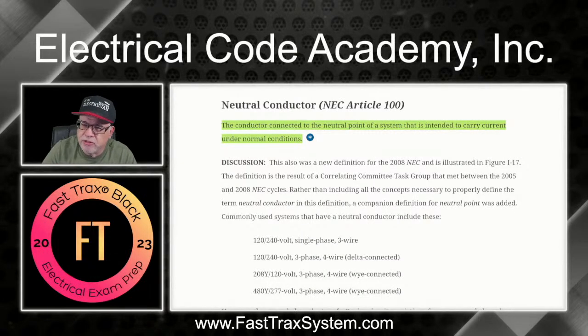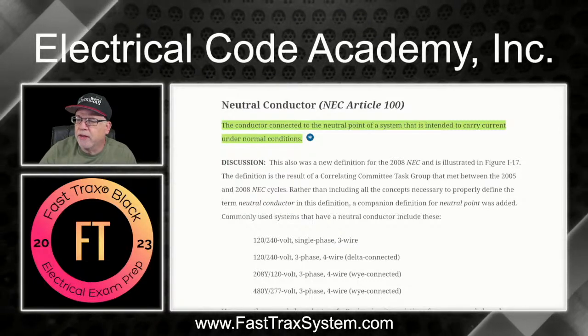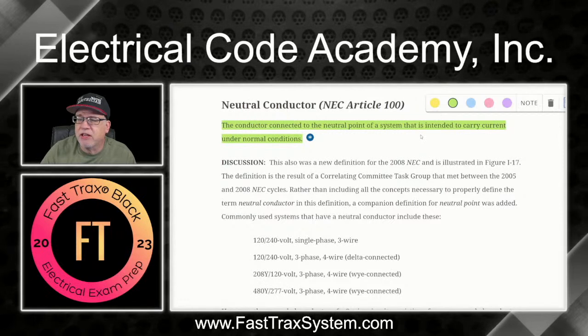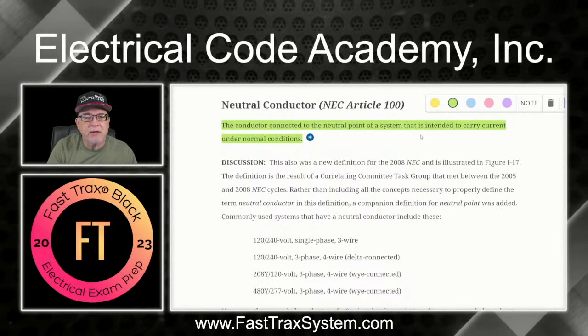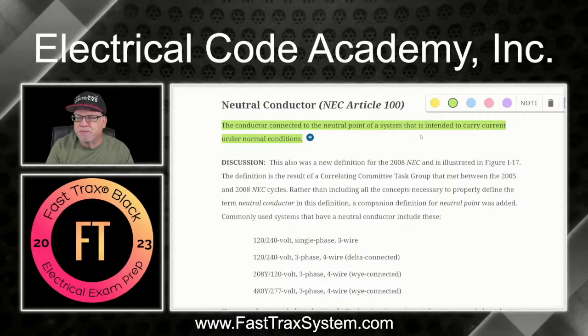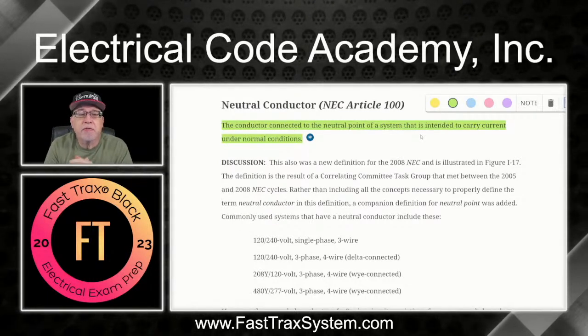Okay. All right, so let's look here. Neutral conductor. What's a neutral conductor? It's the conductor connected to the neutral point of a system that is intended to carry current under normal conditions. So if you think about that, it's that white conductor or that gray conductor or that conductor with three white or gray stripes other than green. So that conductor is carrying current, and it's expected to carry current.